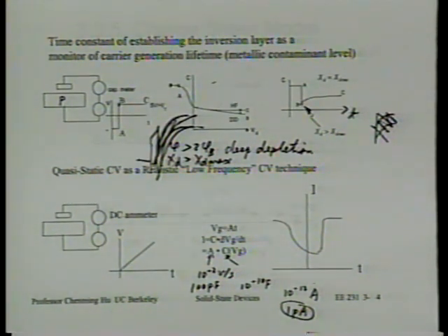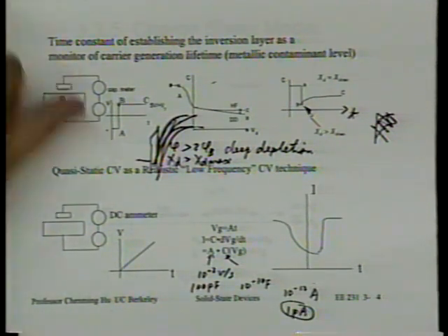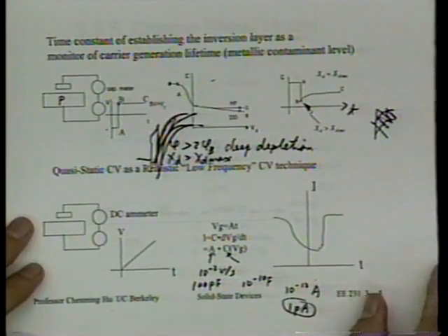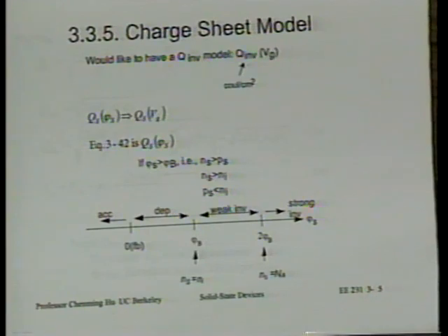The idea is to use essentially a plasma as the electrode, okay, and use the dark region as the dielectric. That's one way of doing it, if you can imagine. All right. Alternative would be simply putting a piece of metal electrode close to the silicon surface with an air gap in between. Right? So those are the ways you could even try to monitor the contamination without growing oxide and putting down metal dots, even simpler. Right? But of course, it's not easy to do that, but it can be done. Okay? All right, questions about CV?